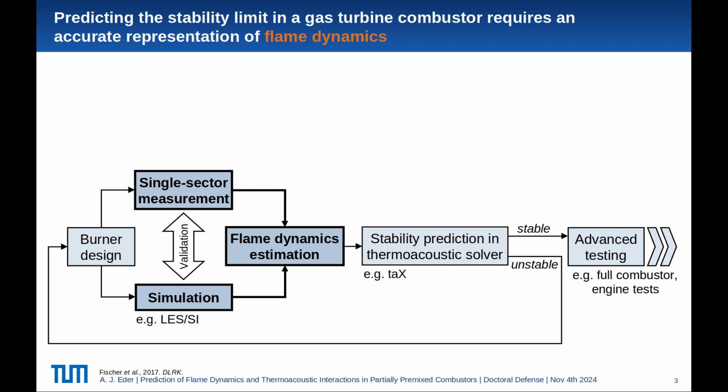In the first step, a reduced order model of flame dynamics is estimated based on measurements and simulations. And in the second step, the acoustic field produced by the flame is assessed by using a thermoacoustic solver. And if the burner design is found to be stable, one can go to advanced testing. If it's found to be unstable, one can iterate. Therefore, there is a growing interest in developing flexible, consistent and accurate tools for predicting flame dynamics with the objective of optimizing stability margins at an early stage of the design process. And this is where my work comes into play.